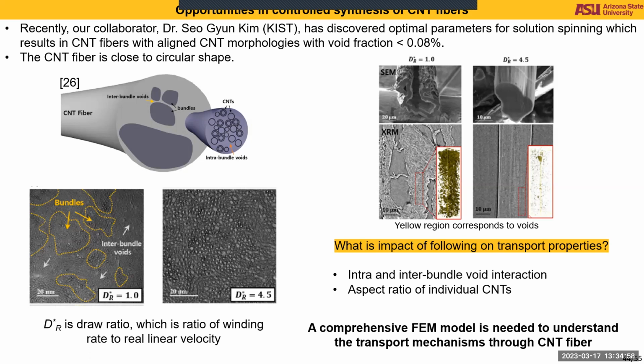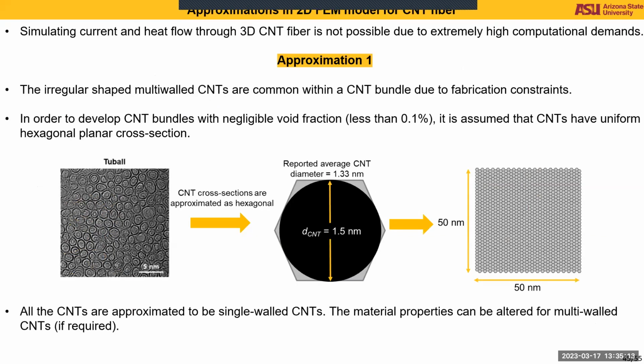So this gives us an opportunity to understand how the transport properties are affected by intrabundle and interbundle voids, and how the aspect ratio of individual CNTs affect the transport properties. For that, we developed a pseudo FEM model. Obviously, if you want to simulate a very high aspect ratio model, it can take forever due to tremendous computational demands. So to do that, we have to make certain approximations.